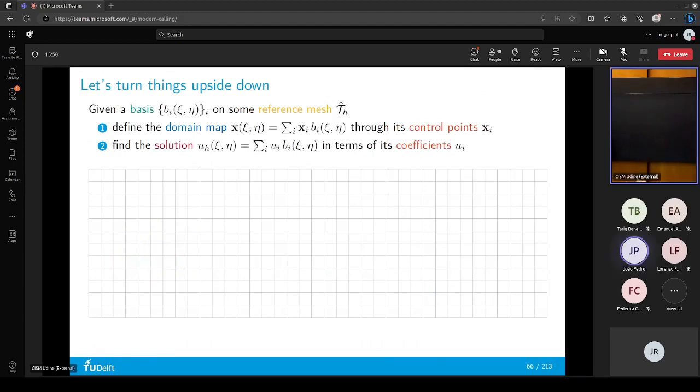So the point I want to make is this: being given magically a domain and trying to fill it from inside with elements is the textbook FEM version, but the IGA thing is more that we define the playground or the toys that we have, the basis, in the sandbox, and then we can move these toys from the sandbox into the real world, but only in the way these toys operate. If they are linear, we can only represent straight-sided lines. If they're quadratic, we can only represent up to quadratic domains.